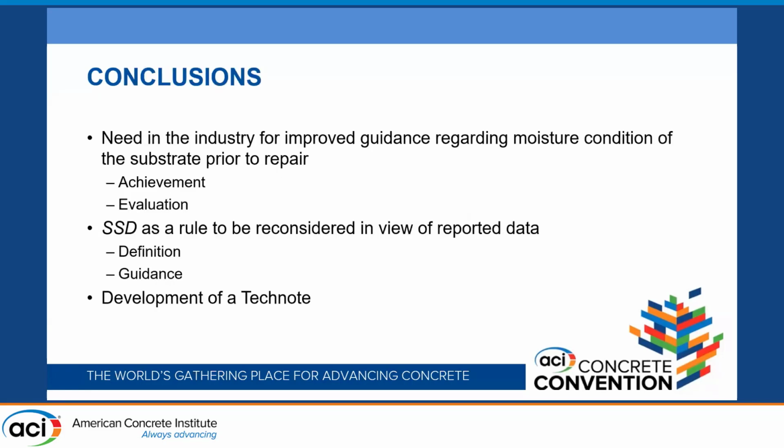With that being said, there is a need in industry to improve the guideline regarding the moisture condition of the substrate prior to repair: what we need to achieve and how to evaluate that condition. SSD as a rule needs to be reconsidered in view of the reported data and additional literature review that we may need to do. As I mentioned in the beginning of this presentation, we're currently developing a tech note to address this gap in the repair world.